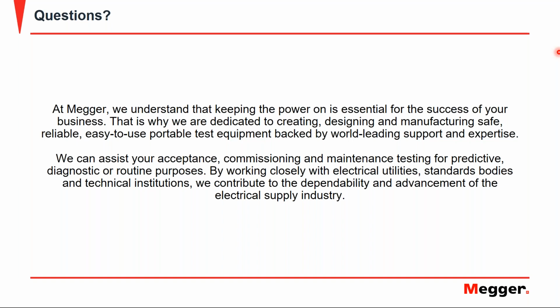Like Charles has mentioned, there are several wave shapes which you can apply on a cable. What we normally recommend for new cables is that you should apply the VLFCR wave shape or VLF wave shapes, because it needs to withstand the voltage. If you have aged cables, which could be a very old paper cable or maybe a water treed XLPE cable, then you certainly do not want to overstress the cable. In that case, if you use VLFCR or resonance testing with overvoltages or VLF sine wave with overvoltages, you can damage the cable and you can have failures during testing or post-test failures.